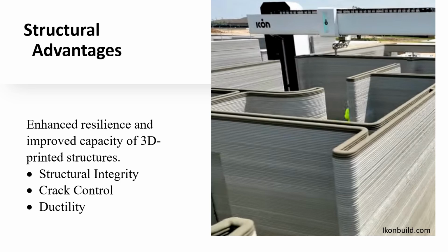Crack control. Steel fibers help control and limit cracking in 3D printed structures. The layer by layer printing process can introduce weaknesses, and steel fibers mitigate this by acting as a mesh, restricting crack propagation and improving the durability of structures.